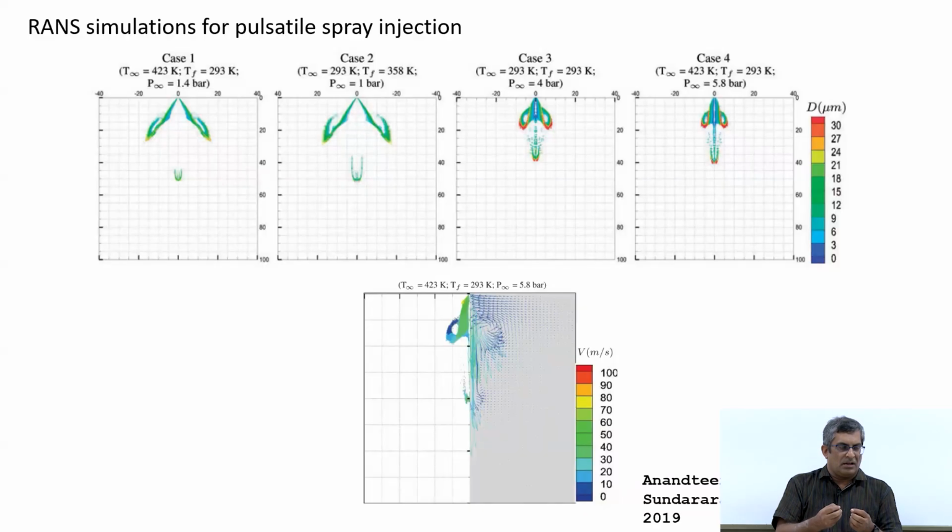That is why you see the presence of the air velocity, even if the initial air velocity was 0 or the spray was injected into a stagnant ambient condition. But because the particles and the surrounding flow are two-way coupled, which is always the case in case of a spray, because of the motion of the particles, the gas flow sets in. Basically, you can see the spray structure, how it changes for different operating conditions.